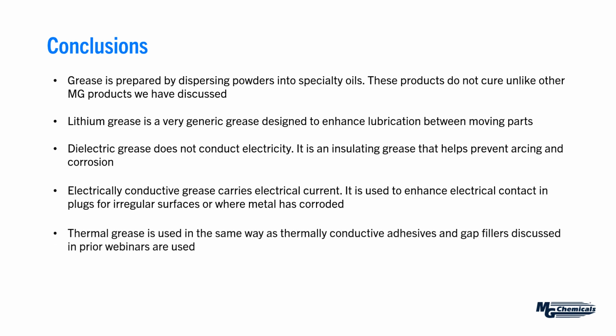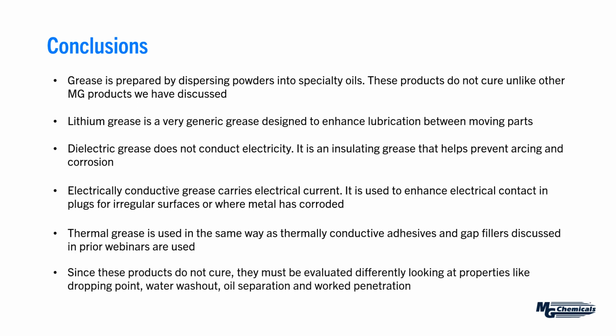Thermal grease, and again, this wasn't really a new idea because we've covered it quite a few times already with the adhesives and the RTVs. It's used in the same way where we're looking to displace the air at the interface of a heat generating component and a heatsink. And since these products do not cure, we have to evaluate them from a different perspective.